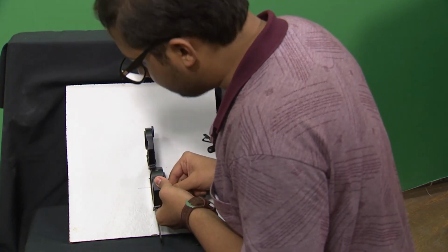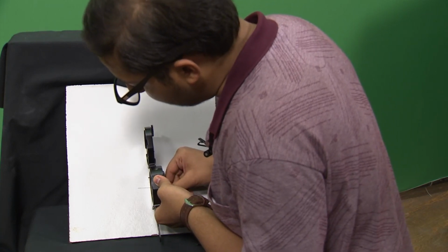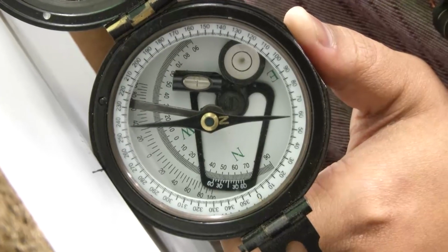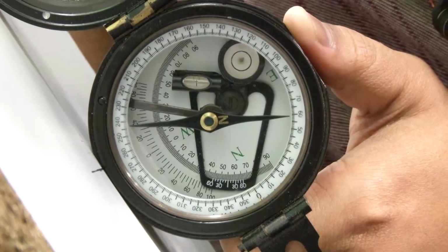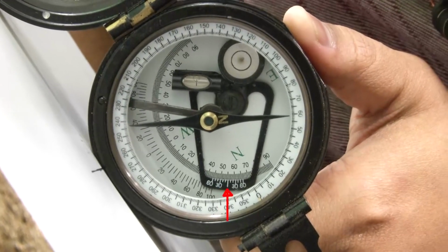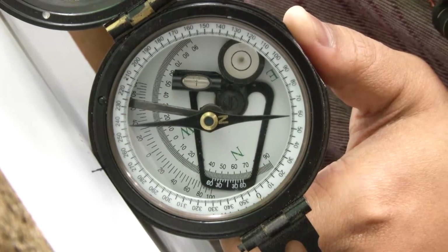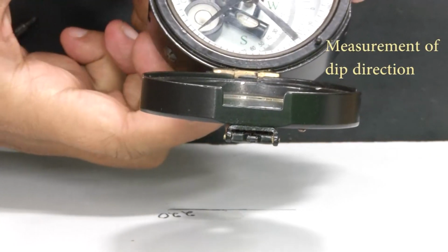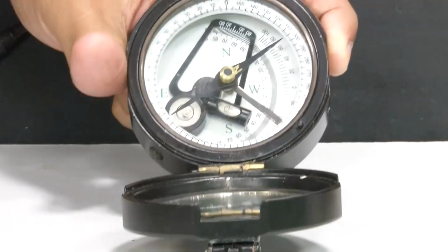Then we adjust the back lever of the compass so that the bubble in the elongated level comes in the center. When the bubble in the elongated level has come in the center, the dip value is the value with which the 0 mark in the vernier coincides with the 180 degree graduated scale, and in our case the dip is 55 degrees.